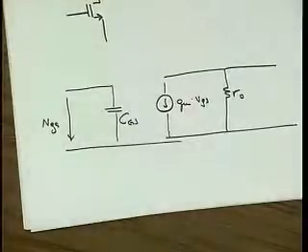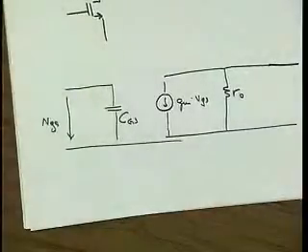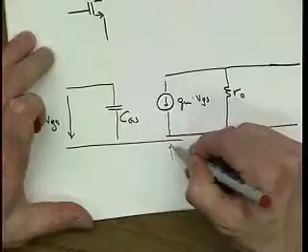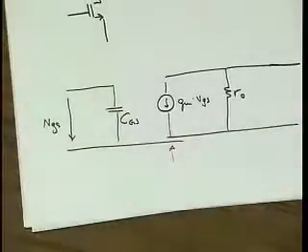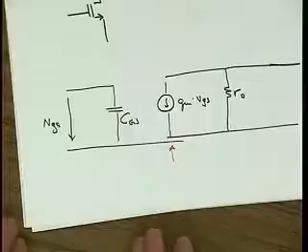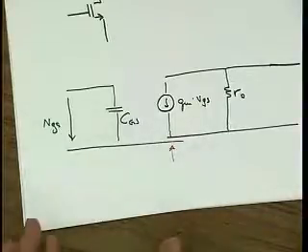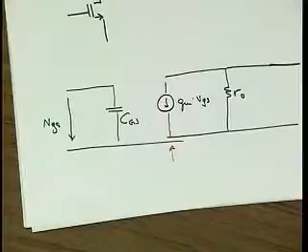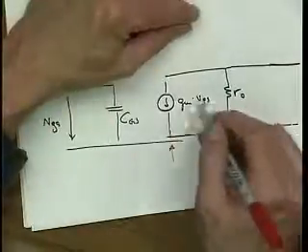Okay, so what are the noise sources here? Well, this guy here is really the big one. If we put the transistor in saturation, it acts like a current source, but the channel itself is a resistive thing. And so we would expect it to exhibit thermal noise, and lo and behold, it does.